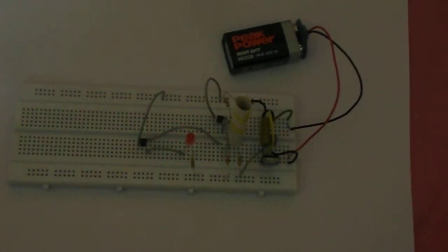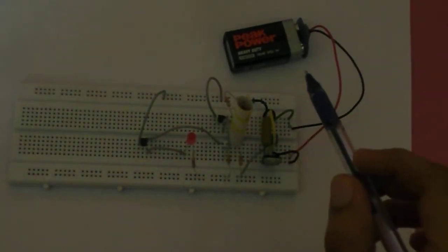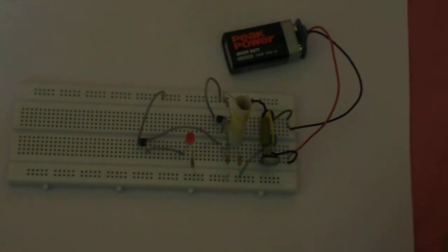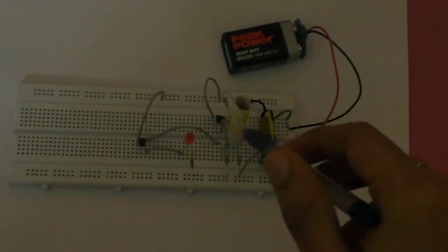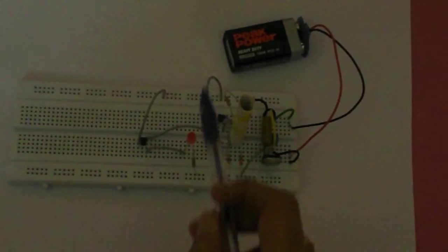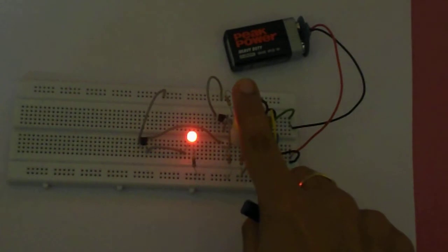and when there's ambient light, the LED does not glow. When I cover the ambient light, the LED glows. I remove my hand, there's ambient light going in through there, the photoresistor is activated, and current is bypassed from this first transistor, and it does not move to the subsequent portions of the circuit. But when I put my hand, cover the photoresistor, then current passes through the transistor through the rest of the circuit, and the circuit is completed, and the LED glows up,